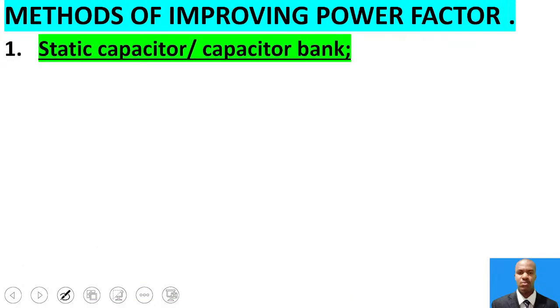In this method, power factor is improved by connecting a static capacitor in parallel with the equipment operating at lagging power factor.